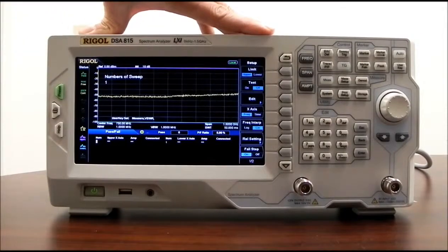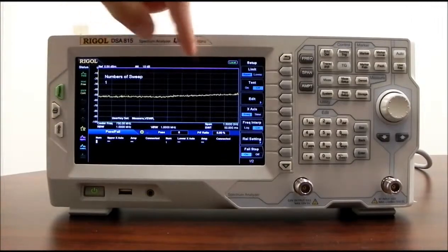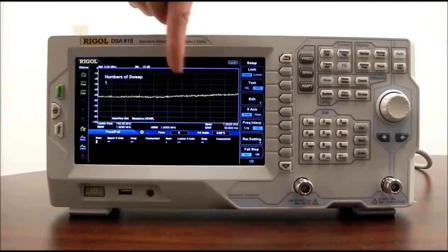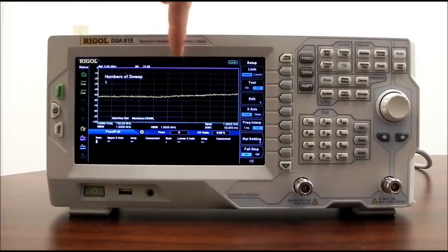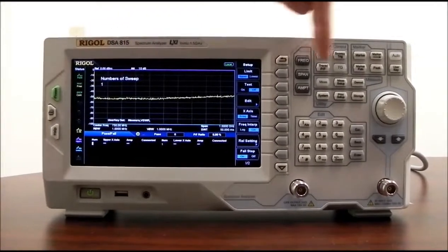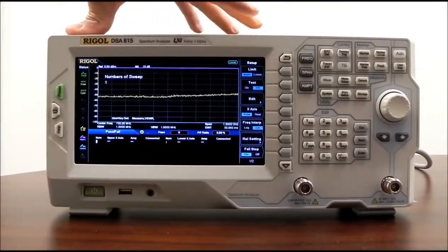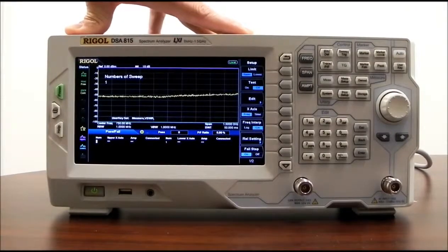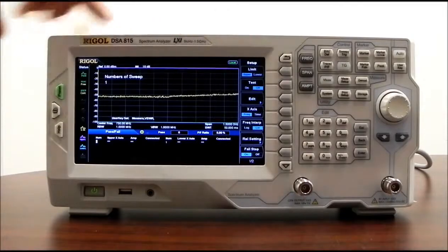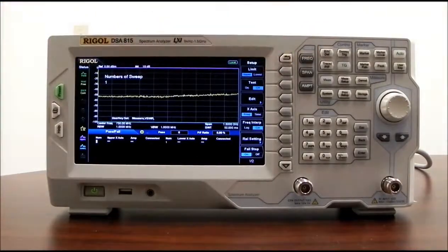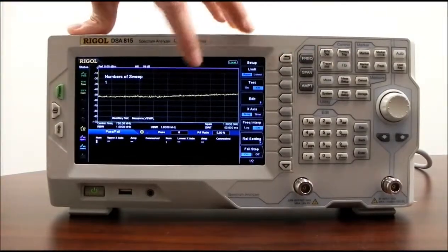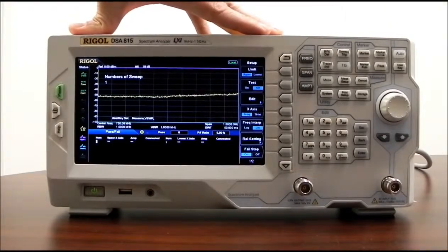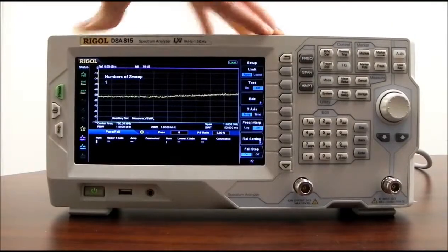You can use this to edit and actually build around a particular channel. Let's say we were doing frequency modulation. We could build a window around the frequency modulation. If that frequency went outside of the upper limit, it would be a fail. Or we could also use the limit lines, upper limit lines especially, for EMI and EMC compliance. We can have a dB value that cannot be exceeded at a particular frequency range, and if we were to pass over that value, we would have a failure.